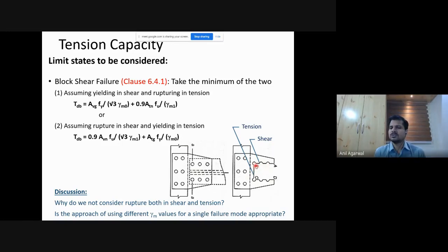So we will assume that one of them has higher stiffness than the other. That means that one will be attracting more stress, and the other one will not be attracting as much stress, and that one will yield first. So either AB will yield first or BC will yield first, and the other one would not have yielded. Fine. So let's say AB has yielded first. So the surface that is in shear has yielded first. BC has not yielded yet.